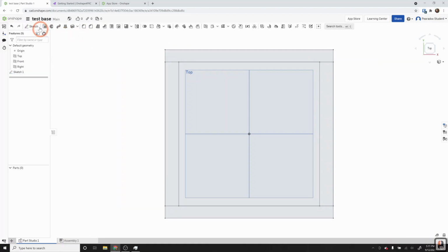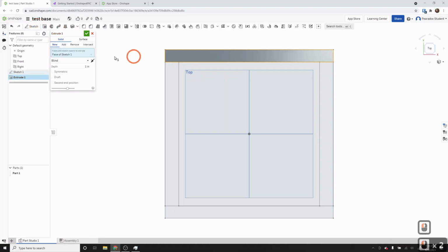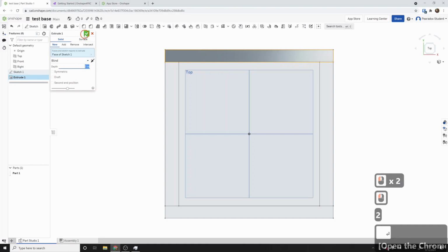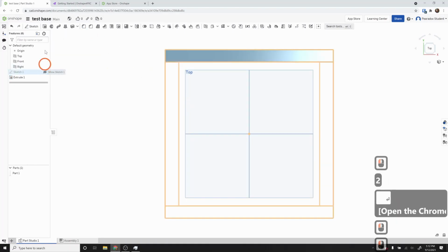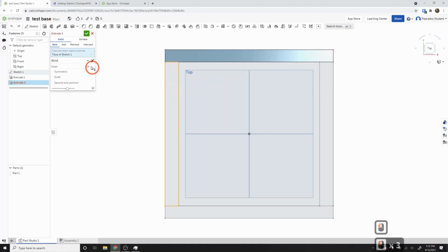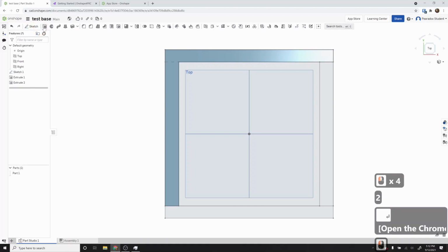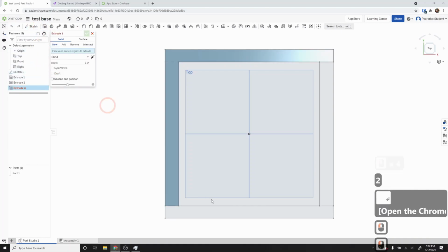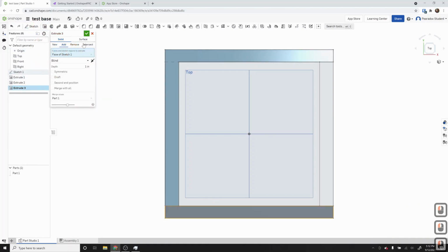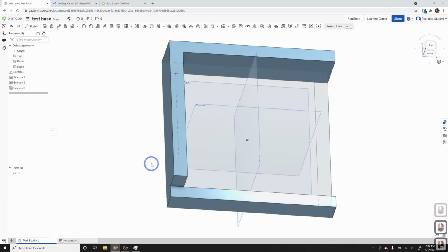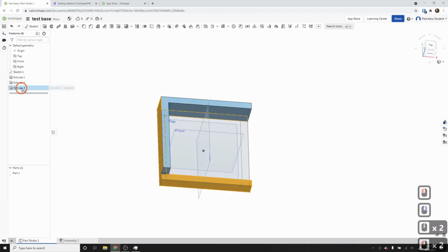And so we could complete this sketch and we could go extrude every one of these. They need to be 2 inches. So new. And then I have to go unhide the sketch, and I could do this one and also do this for 2 inches. And I'd have to do the same thing again for this one, new. I'm not going to do it as 2 inches, but you can see, whoops, I did those all as add somehow, even though I was saying to do them as new. Just didn't click.